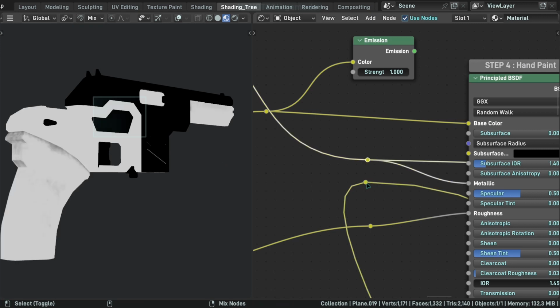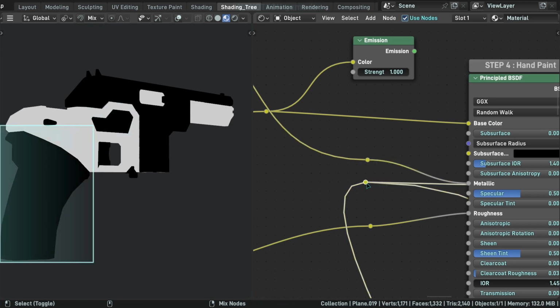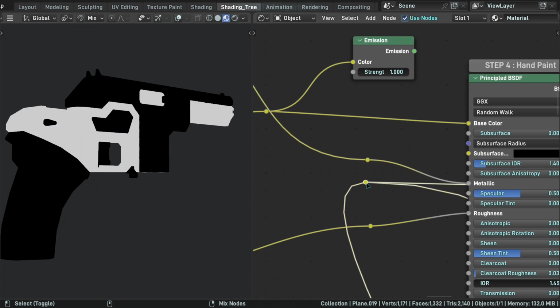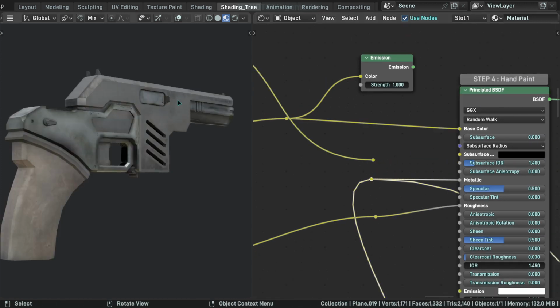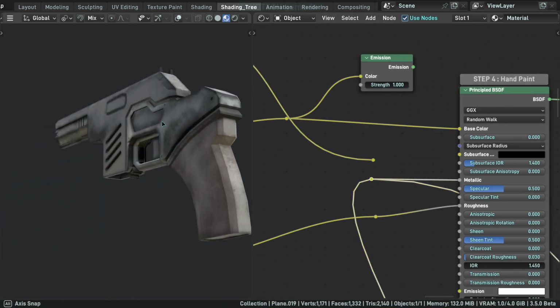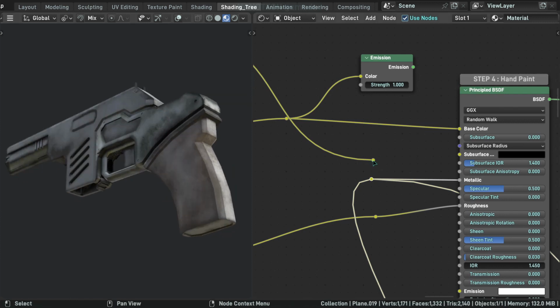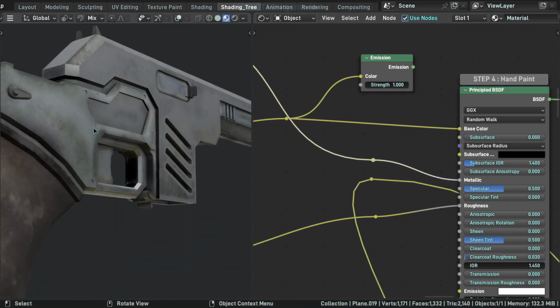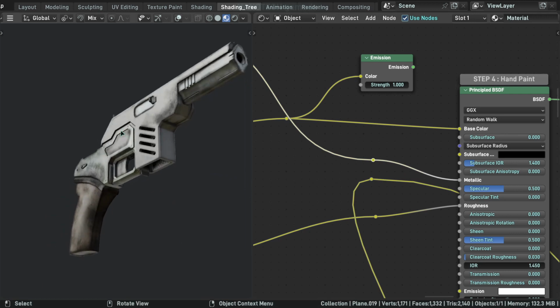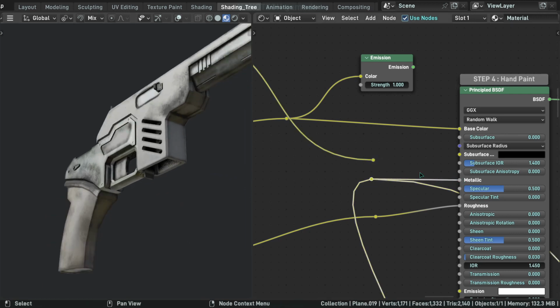You can see I increased the range of the metallic map and painted the handle as well. So let me plug the metallic map from step 3 so you can see the difference on the shader. Metallic maps greatly influence the specular colors. As you can see here, the handle specular is white when we have no metallic, and brownish now that we have assigned it metallic values. This is simulated from the metallic surfaces of the real world on the Principled BSDF automatically.